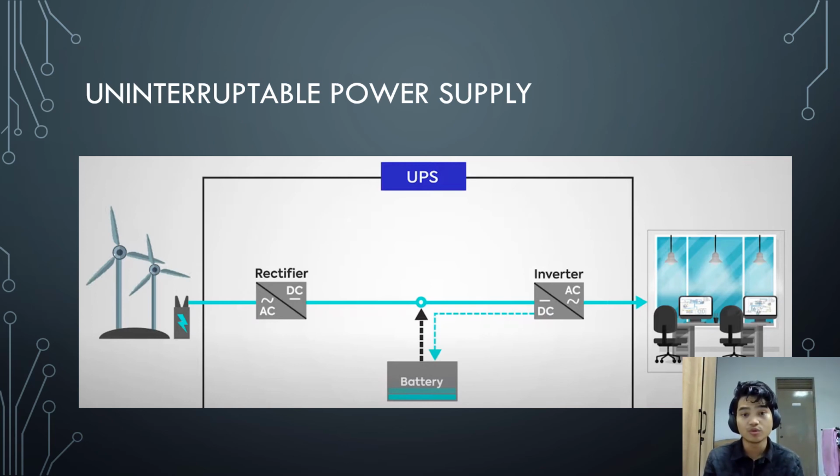But obviously this comes with its own set of power losses. As we know, there are conversion losses when you're rectifying and inverting it back, and there are also battery charging losses. But it does provide good conformity of the voltage. So that's the price you pay, and that's what you're getting back in return, which I feel is a good implementation in this particular application.